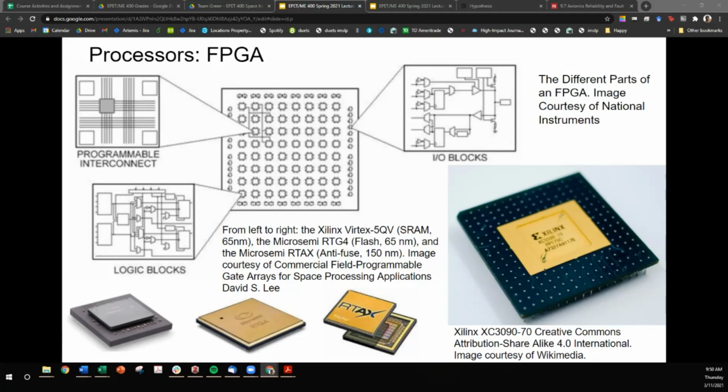The CPUs and the GPUs are these transistors where you're sending these transient electrical signals, and after the electrical signal passes, there really is no memory retention. Whereas FPGAs are encoded such that their circuits are physically in that shape to allow signals to go through and process consistently. So for that reason, FPGAs can be more resilient in radiation-heavy environments.